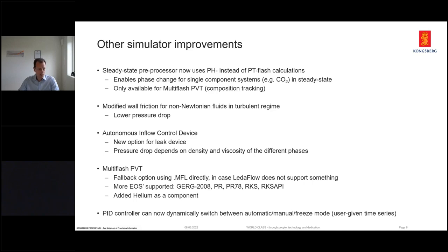Multi-flash PVT has some more options. Now we have a fallback option in case LedaFlow doesn't support a certain equation of state or any other option in multi-flash. It's possible to let multi-flash read the multi-flash file that contains the fluid configuration. It can be read directly by multi-flash, so that is quite useful as a fallback. And also we're supporting some more equations of state now, like GERG 2008, which can be nice for CO2 with impurities, and some old legacy Peng-Robinson and SRK equations of state. And also helium has been added as a component because that was a request by one of our customers.